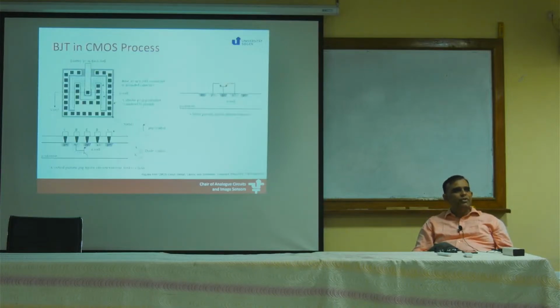Now we also said you could use a BJT in making a commercial temperature sensor. Now BJTs don't exist in a CMOS process, because we would have made a chip with just N-type diffusion in a P-type substrate. Remember the other day we saw how a chip is made in a CMOS process. But BJTs do exist as parasitic elements here.